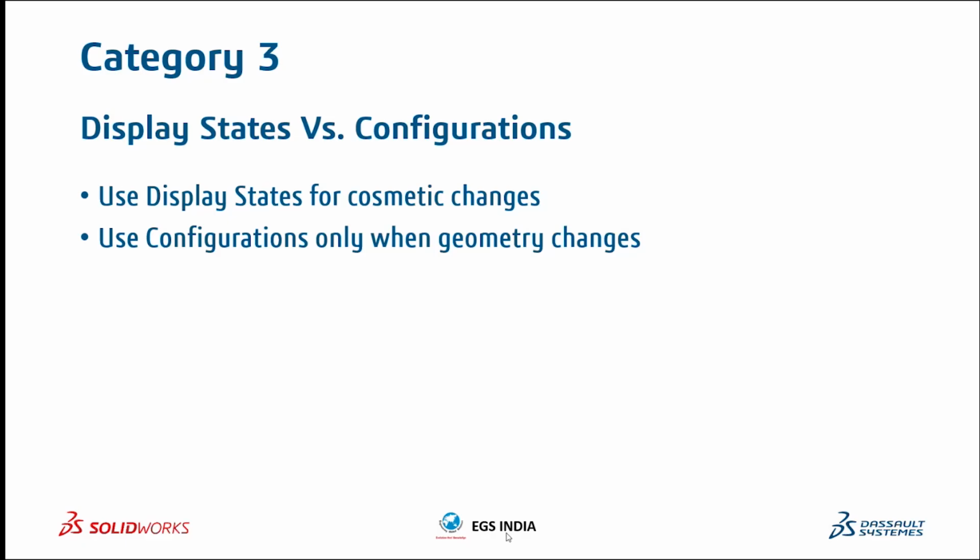While configurations are very helpful when you are controlling geometry or features, when we only want to see how it looks in different colors, or you only want to control visual aspects like appearance and visibility, you do not need to rebuild or reload the entire model data. That is why, for any change that is to be done only cosmetically, we prefer to always go for display states rather than creating new configurations. Within the same configuration, you can create multiple display states to show different types of cosmetic changes. So this is the recommendation when it comes to appearances.